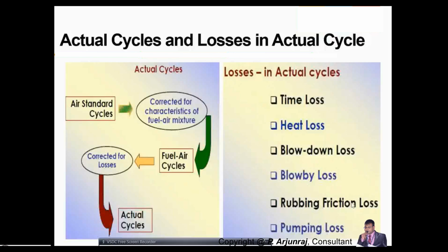When the engine is running at higher RPM, all the moving parts, such as the piston, crankshaft, camshaft, and turbocharger turbine, will develop friction. So you need to reduce that in order to get a higher percentage of output. When I say output, the maximum you can get is 40 or 45 percent efficiency for a diesel engine, and 30 percent for a gasoline engine. If you reduce the friction loss, then you are able to increase the percentage improvement with respect to efficiency.